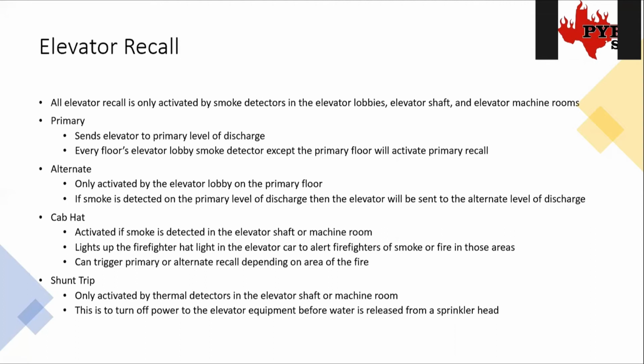I'm going to go ahead and move on to cab hat, because I think if I talk any more, I'm going to make it more confusing. Your cab hat: if you're in an elevator car and you look at all the little circles and lights that are there for your buttons, one of them looks like a firefighter's hat, and it'll light up. Well, if it's lit up, you probably shouldn't be in the elevator car.